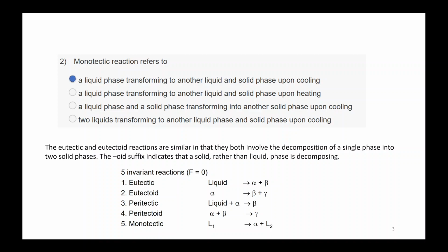But in terms of the engineering graph, up to UTS you show that strain hardening is taking place, but it is occurring in the entire region. But your cross section is reducing, so that's why your curve comes down. Strain hardening is taking place in the entire region, but from an engineering viewpoint we mainly focus on the yield point to the ultimate point.